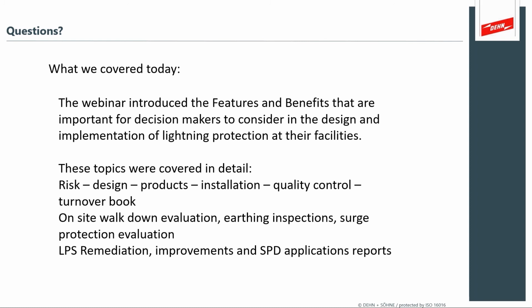Can the clamping meter that you showed also be used to measure lightning conductor loops? What is the maximum loop impedance that is acceptable? I believe the question is, can you evaluate your lightning conductor? Yes, you can evaluate the loop that the lightning conductor sees both above ground and below ground.